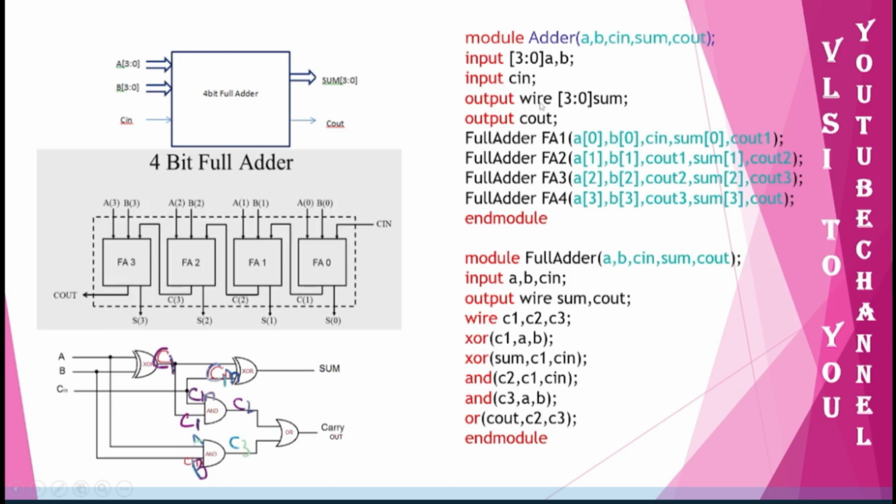You can just mention it as wire. Since you are having internal connections here, instead of mentioning every internal connection, you are just mentioning everything as wire. There is nothing wrong in doing that, right? Output wire. So sum is 3 down to 0 wide, and then the C out is 1 bit wide. So this is my structure, and with that structure I have mentioned all the inputs and outputs.